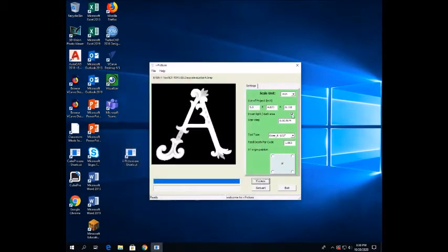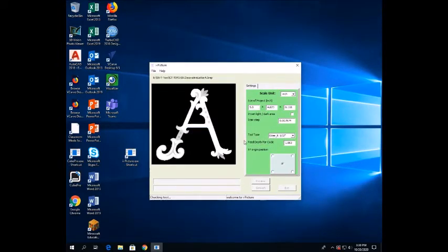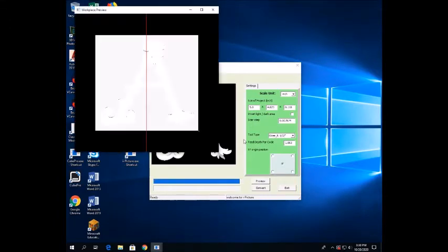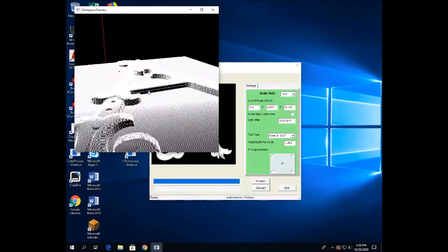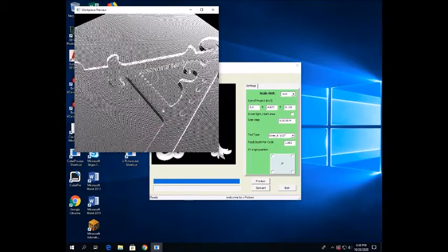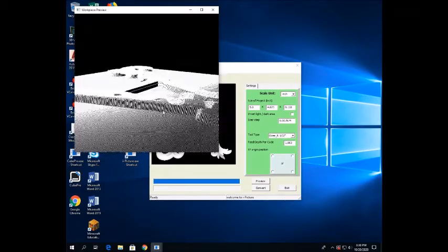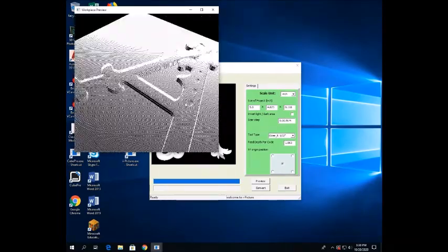We'll just show you the difference if we unclick the invert dark area. In this case, the preview should show us that the lightest areas of the grayscale 3D image will be at the top of our project, and the dark areas will be machined out of the wood itself. And there you have the difference in their inverted value. Now we have the lightest parts of our image being the highest points, and the darkest part of the image being our maximum project depth.